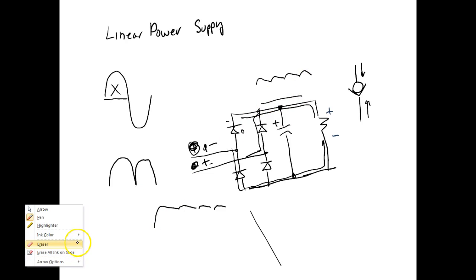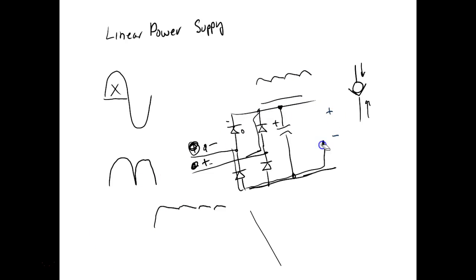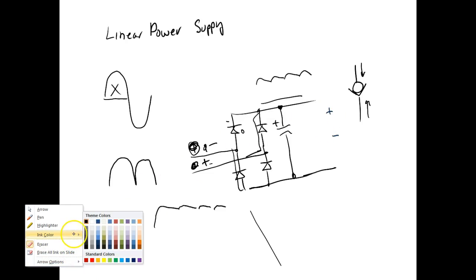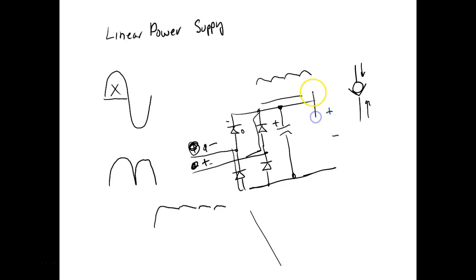And then on this other side, I'm going to run this through a regulator. What a regulator does, well, it regulates this. So this is what you got on your car. And over here, this might be 8 volts. Over this is going to be 5 volts, but it's going to be a nice clean 5 volts. This would be the makeup of a linear power supply.